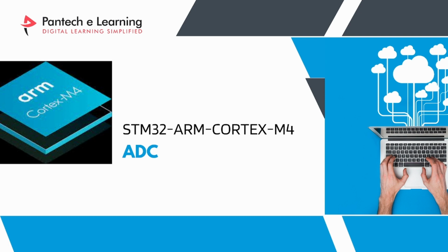What is the sum of the 10-bit? It starts from 0, and the maximum for 10-bit is 1023. So what this ADC is going to do is convert the 0 to 3.0 volt range to a digital value which ranges from 0 to 1023. This is the process that the ADC performs.